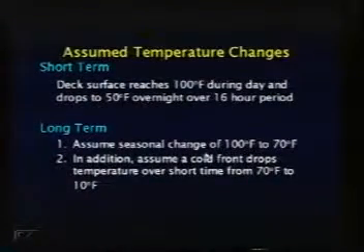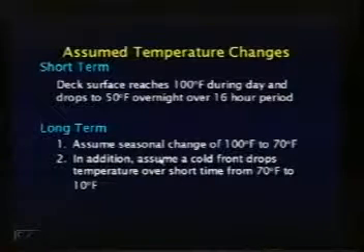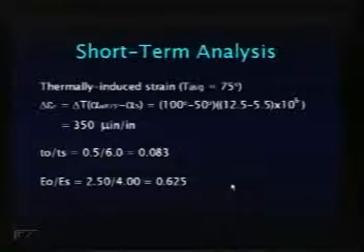Then in addition, superimposed on that, we would assume that a cold front moves in and drops the temperature over a very short time from about 70 degrees down to 10 degrees Fahrenheit. And the thermally induced strain, looking first of all at the short-term analysis, it's pretty easy to calculate if you remember your physics. You take the change in temperature, times the difference in coefficient of thermal expansion.